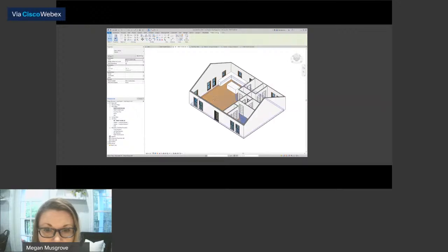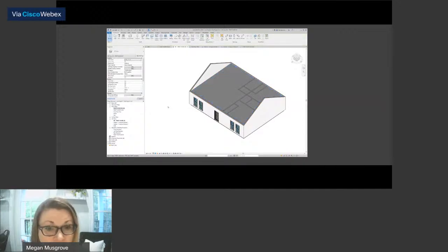I did something weird. It's on the first floor. Thought I changed that. Okay. Well, that's a good example of it didn't do what I wanted it to do. It's still sitting on the first floor plan. So we're going to change that to first floor ceiling. You can hit apply, but it already did it. Now, there we have a ceiling.